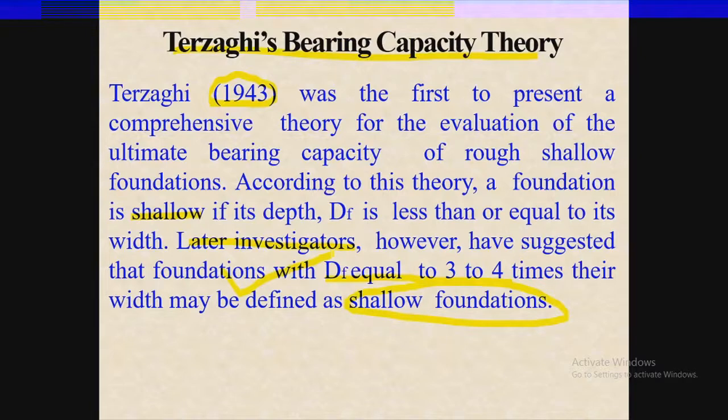For now, just keep in mind that for the very first time Terzaghi gave us the evaluation of ultimate bearing capacity for a rough shallow foundation, because that is the biggest assumption of the Terzaghi bearing capacity: that the base of the foundation is rough and the foundation is shallow.